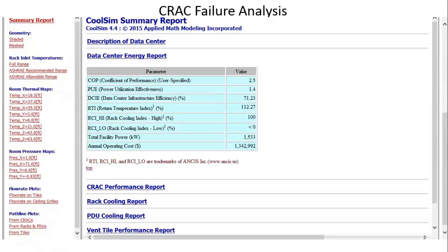That's right. Because if you go into a failure mode, the racks are still going to want whatever it is that they need. And like I said, they need about 156 CFM per kW, worst case, at a 20-degree delta. They're always going to want that. And sometimes it's more than that because they often build the fans bigger than is required.